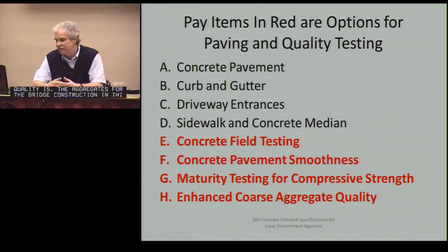The consultant called me up and said he'd like to use granite aggregate in some of his sidewalks. The worst place to have the pop-outs we get from the glacial aggregates is in the sidewalks and by church and things of that nature, where the women in their high heels might catch them and twist an ankle or something. Roads and things can live with more pop-outs because you get cars and vehicles traveling across it.